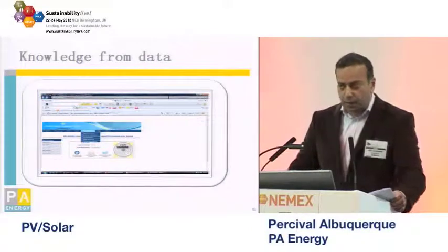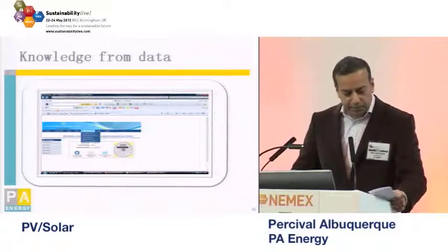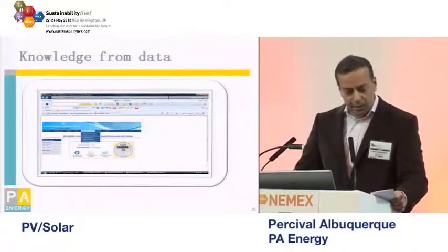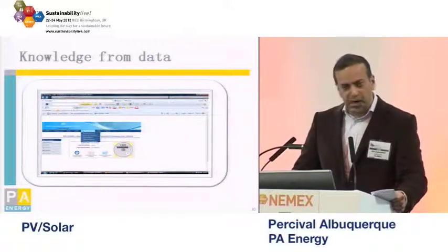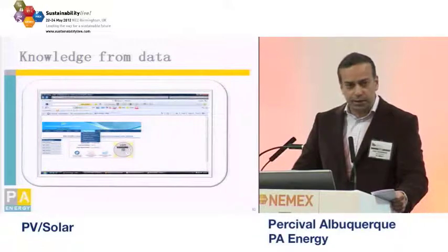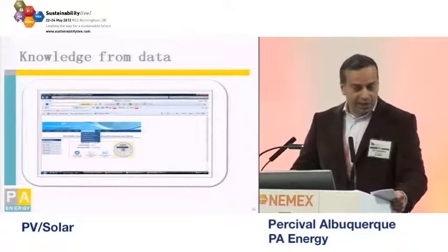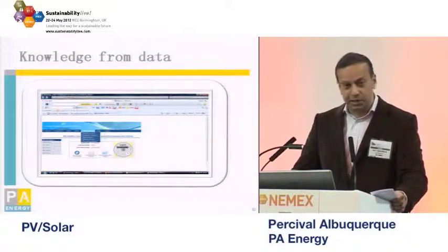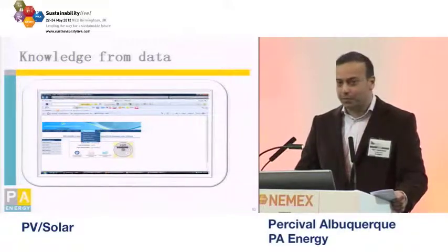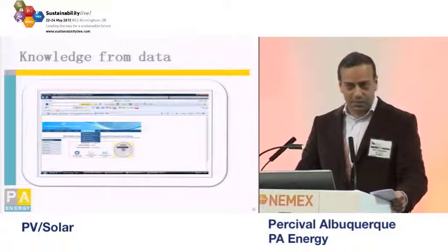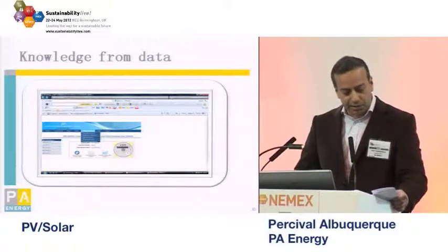And with the web-based systems, you can get a whole range of information from them. So for example, if you want to get daily meter readings, you can log on and look at the daily meter readings. You can also do benchmarking. So if you have several sites, you can actually overlay one site on top of the other to see how they're performing. You might have a couple of buildings which are in very close vicinity to each other, and you might want to ensure that the performance is similar, especially if the design is similar. And if the performance is different, then there are obviously questions to be asked.